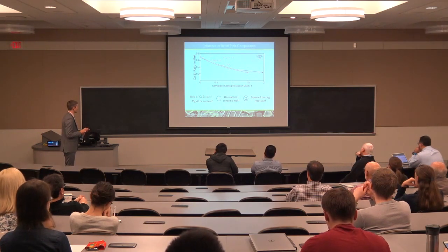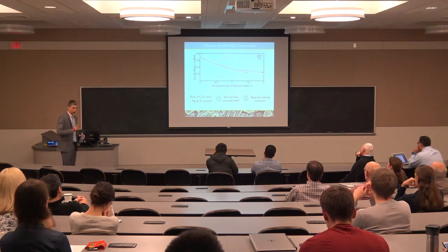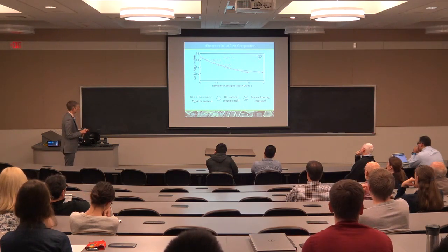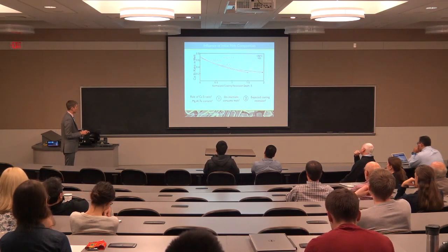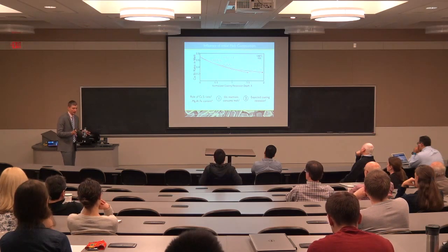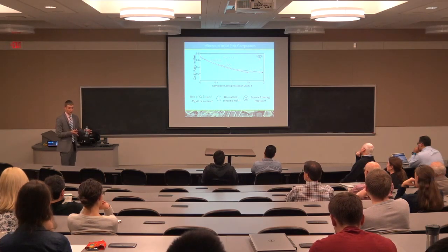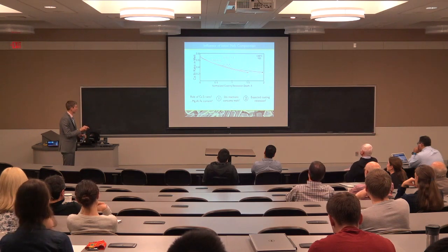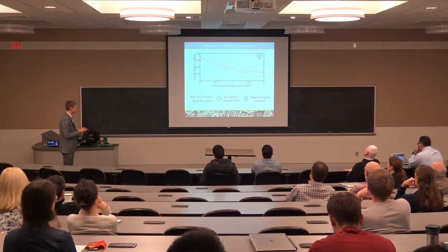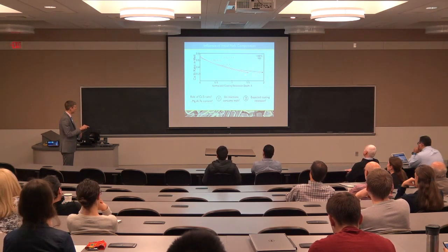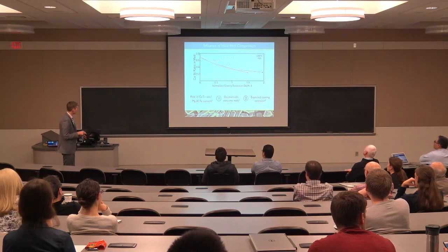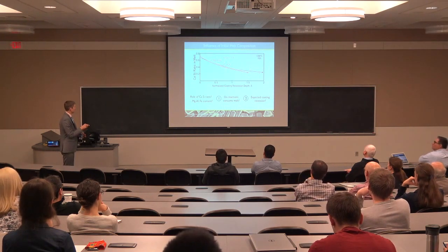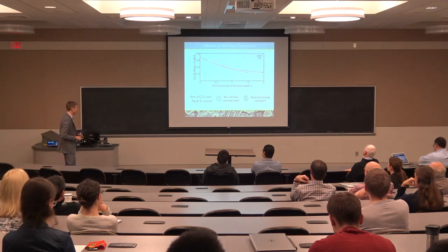I'm showing three here. In this case, they all had similar initial calcium-silicon ratios, and we see that for the most part, they follow similar trends. There are some deviations at the very end of the reaction, where we hit some other phase fields that either extend or contract the total amount of recession that happens. But we get a cluster of recession depths that are out here, and these are all pretty bad. So this says that these particularly calcium-rich melts are probably some of the most problematic.